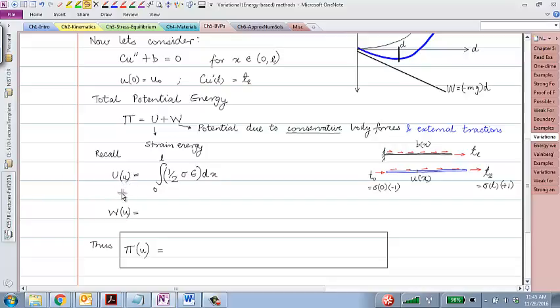Okay, and I can write stress as a function of strain here as well. So as an alternate expression, you could write that as half times c u prime. That's stress, and strain is u prime. So that entire thing is strain energy density. If I multiply that with the volume, which in this case, since we are assuming area constant, I'll just take x integral between 0 to L. That would be the total strain energy stored in a bar.